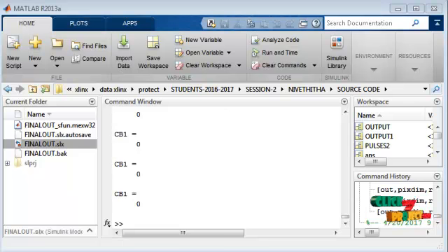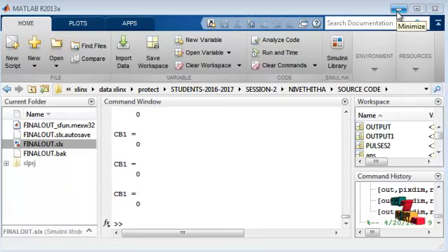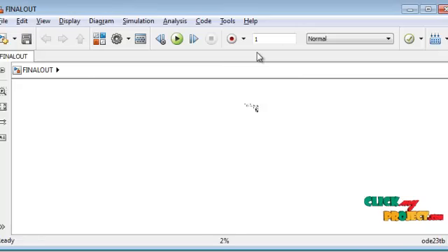Next we see the running process of our project. This proposed implementation is done in the MATLAB simulating environment. First open the MATLAB window and create a new model file. After creating the new model file, we arrange the elements as per the circuit diagram from the simulink library browser. In the library browser, various blocks are available. Our required blocks are Sim Power Systems and commonly used blocks. From those blocks we get the elements and arrange the circuit as per the base paper. After arranging that, we click the run icon. The corresponding scope will show the corresponding output of voltage, current and such parameters.